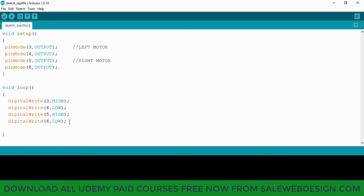Next, if you want, you can put a short delay over here. I will just put a short delay of 2000. But even though we have given a delay of 2000, this delay will not execute, because when we run the program, since the program is in a void loop, the program will come to the last line, that is delay 2000, and again it will start executing from the top. So this program will keep on executing again and again, and our motors will continuously move in the forward direction. So guys, I have basically finished with the program.